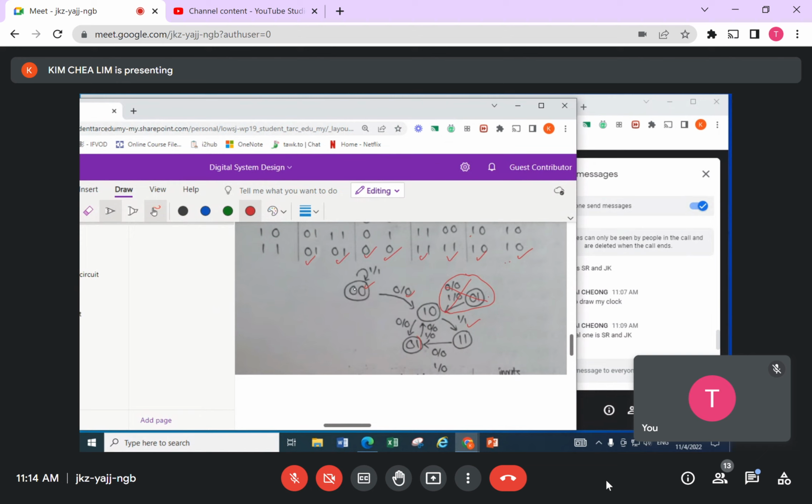That is to say that my 0, 0 here actually is an unused state, something like a don't care. So if you start from here, you must make sure you put an input to it so that it joins back the main loop. If it's 1, you input a 1 here, they always stay in this loop. And with this output 1 here, they can set it to an alarm, for example. Hey, how come my output is always 1? Because it is in this state here, which is not moving on.